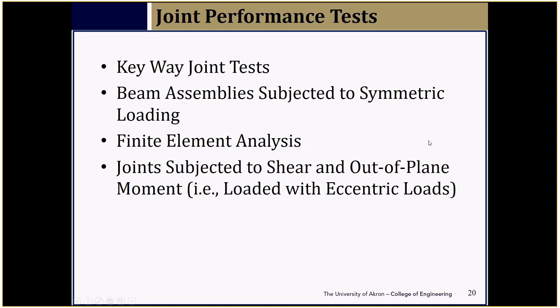Then we realized that once the beams are acting as single beams without any interaction from the adjacent beam, the beams can also have torsional movement, or there can be torsional deformation. Therefore, we also looked at joints subjected to out of plane movement, which is very critical once the joint has really failed. So these are the types of tests we did.